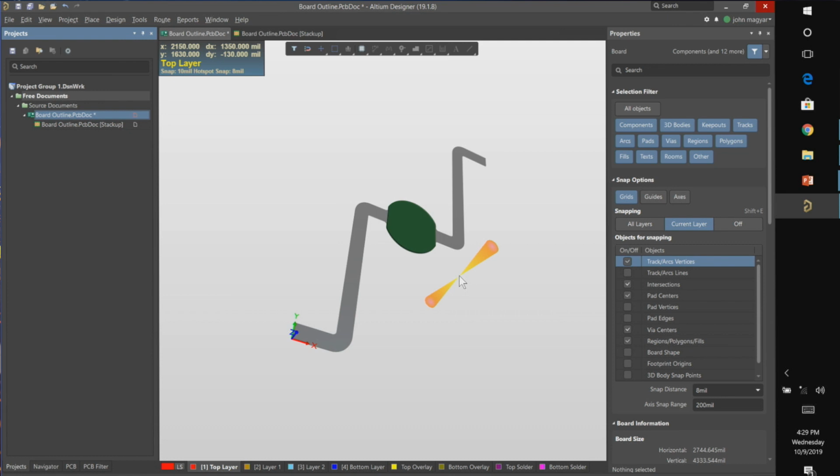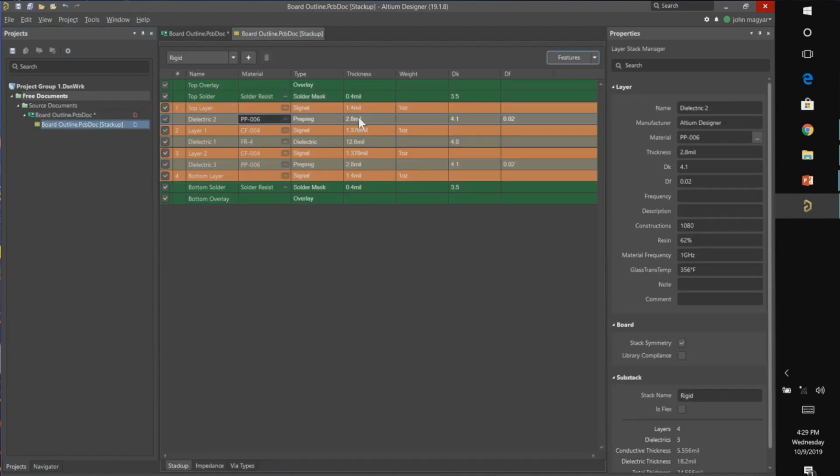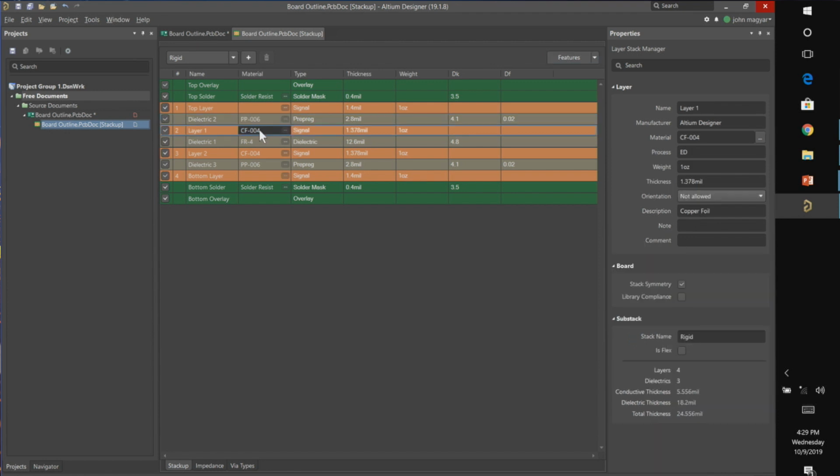So generally, there are two types of flex applications. What they call a single, a one-time bend, where they bend it all up just to get it into a certain configuration. And then the other ones are constant use, where they're always moving in their application. They do have different types, and those are available in the layer stack up. So if we go back to that, you can get, for the rigid layers, notice that they're different from what we just probably have a default for the top.